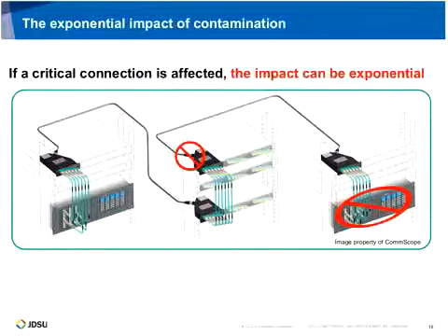And so when you start thinking about dirty connector interfaces, think of that in relation to an MTP or an MPO connector. If you have one of those that happens to be contaminated, now you're not just taking down one single fiber throughout the channel. You run the risk of taking down multiple, up to 72 actually.